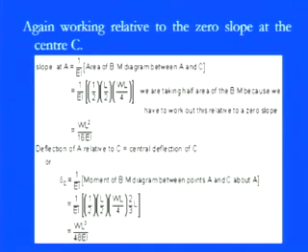This is one area, and then we know the location of the centroid, which was 2/3 of the distance, that is L by 2. And if you are going for the entire triangle, then it is 2/3 of the total distance L. So by keeping those values here, delta C is equal to 1 by EI half L by 2 WL by 4.